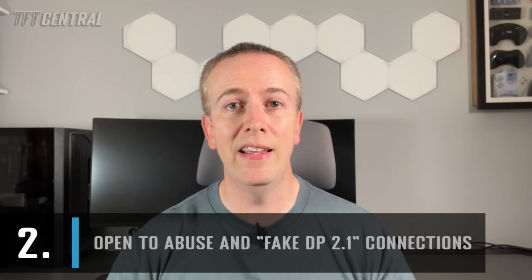According to the VESA specification, for a connection to be called DP 2.1, it doesn't actually need to support any of the new UHBR speeds. The requirements for DP 2.1 certification counterintuitively do not even require the new speeds, which are such a huge focus of the marketing for this new connection, and it just seems mad. This feels like it could be open to potential abuse in the future, although thankfully we've not seen any signs of it so far. It's probably only a matter of time though, as we've already seen fake HDMI 2.1 connections in the past, even from big name suppliers.